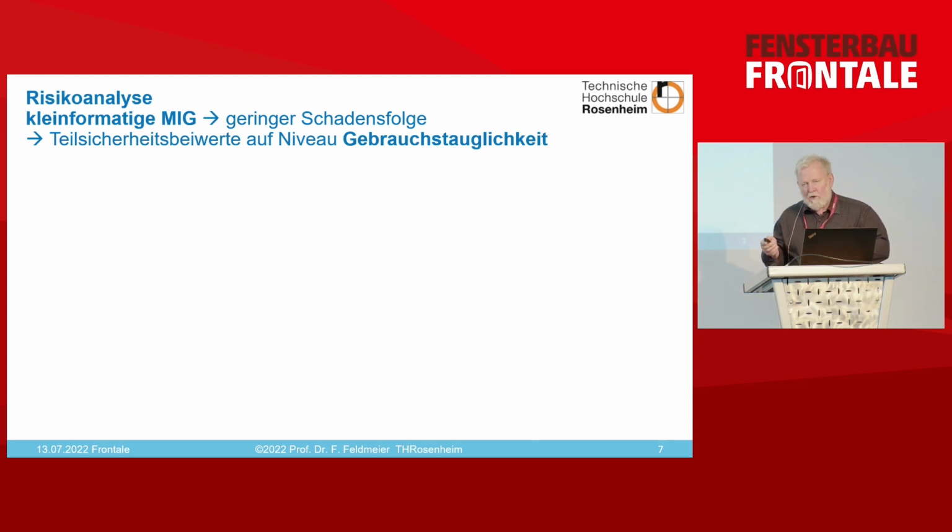There is a risk analysis, and when it comes to small glass pieces, I'm going to have to do a risk analysis, and of course, you can make some assumptions. And in the association, we agreed that when it comes to small sizes, what is small though? So they just decided that it's 2 square meters. So 2 square meters or smaller, which would be small pieces. You just actually need to have the carrying capacity test.